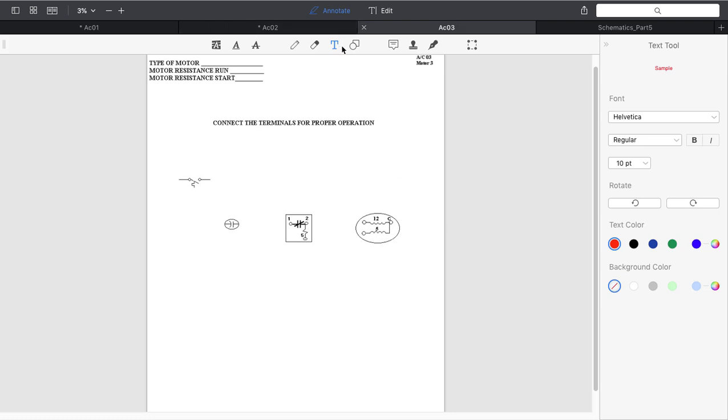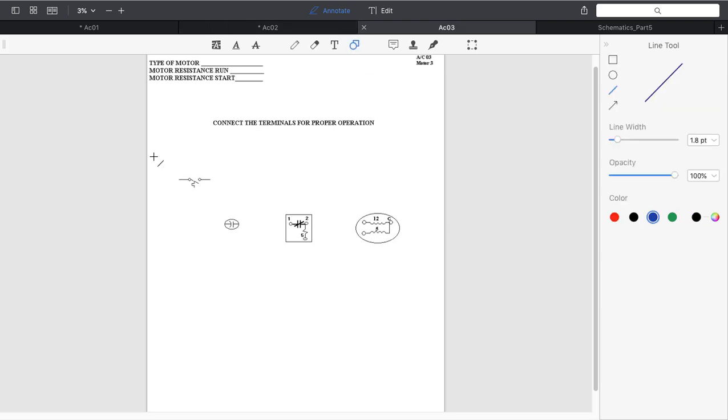Okay, so I'm going to take my lines. I'm going to give myself my line 1, and I'm actually going to go ahead and do my neutral, or my line 2. That's a connection there. I know pin 5 has to connect to common. We're going to go ahead and put that wiring in.